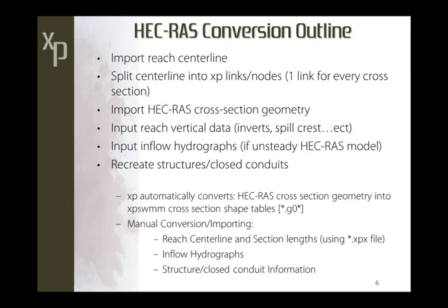An XP model will automatically convert the HEC-RAS cross-section geometry into XP. Now, a more manual conversion or importing will be required to bring in the reach center line and section lengths, the inflow hydrographs, as well as the structure and closed conduit information that's used in HEC-RAS.